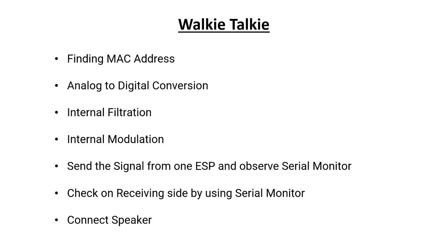That microphone will automatically convert your analog voice to digital. And an I2S power amplifier will automatically convert the digital signal coming from the ESP into an analog signal and then amplify it, and then you can connect the speaker directly. So I hope you got all the things here.